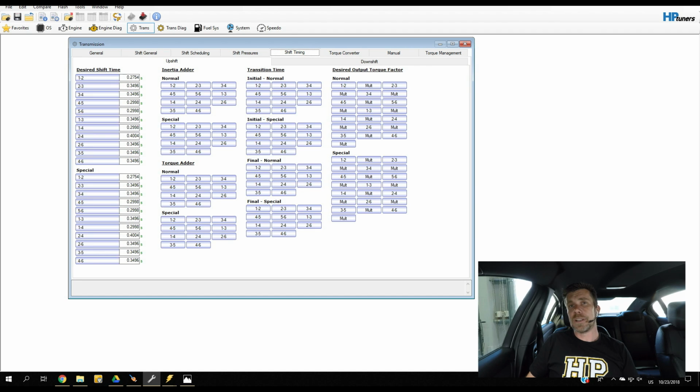So instead, because I'm still competitive, I wanted to go faster than 14.1. I looked at increasing the shift speed, or sharpening up the shift performance. The result of this was, over the course of about 5 or 6 runs, making small iterative changes to the shift speeds and shift points, I managed to get that 14.1 down to about a 13.3. So we're talking about almost a full second without making any more power.